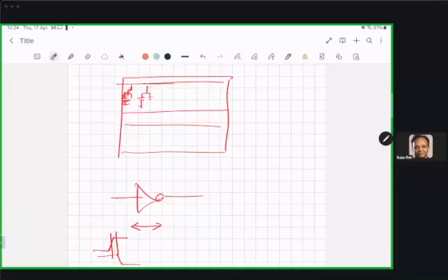Is this fine? So I have an inverter and I'm trying to find out what is the delay provided by this inverter. So when input changes, after how much time the output changes. Now for this kind of, or for that matter, any gate, the delay is a function of what this inverter is connected to. For example, is this inverter driving another inverter? Then the delay will be certain value. If I say that this inverter is driving 3 such inverters, then the delay will be more or less.